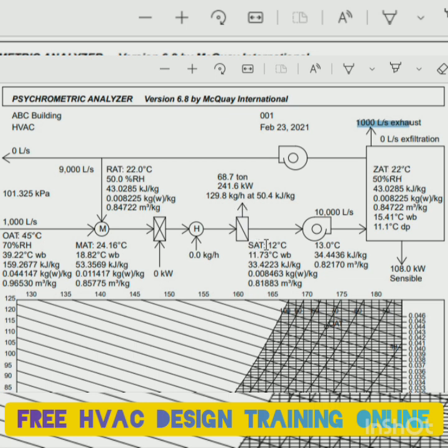Your off coil temperature is 12 degrees Celsius, and your on coil temperature is 24.16. Whenever people ask what the on coil temperature is and what the off coil temperature is, this is your on coil temperature. That means your return air and the mixing is here. This is your mixing chamber, so this is called the on coil temperature. Do not get confused. Always, your mixing air temperature is your on coil temperature.